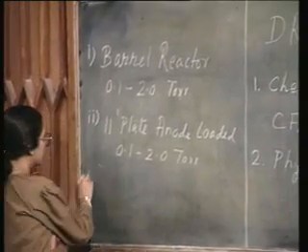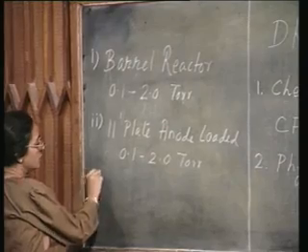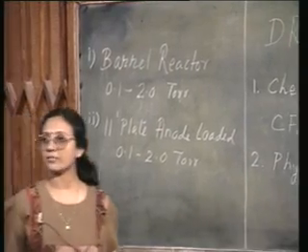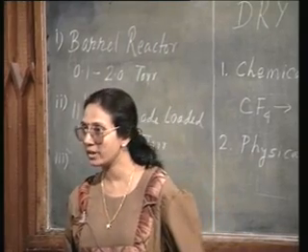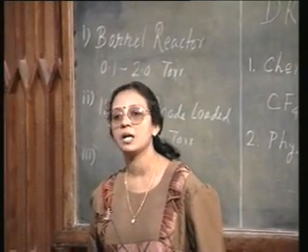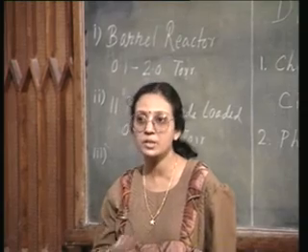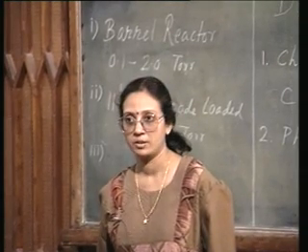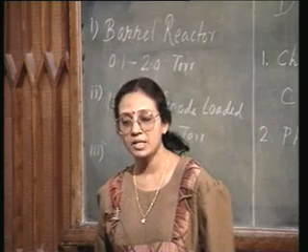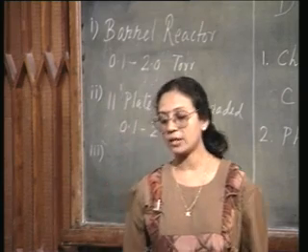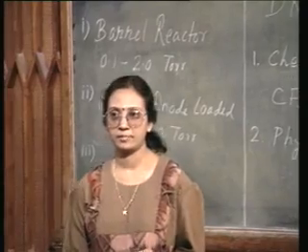The next one in the line is usually called the reactive ion etching system, but as I told you, that again does not convey the actual meaning, because ions hardly ever actually take part in the reaction. So, instead of that we will call it asymmetric parallel plate cathode loaded reactor.